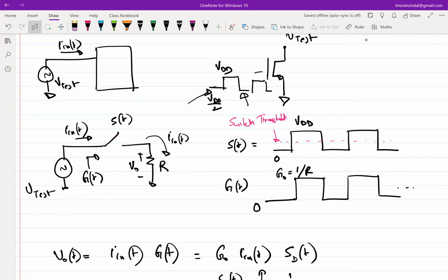On top of that, this is periodically time variant, right? So the characteristics of the switch are periodic. It is because of that periodicity you are getting the tones, right? So because it is periodically time variant also, this is often referred to as an LPTV network, a linear periodically time variant circuit, right?